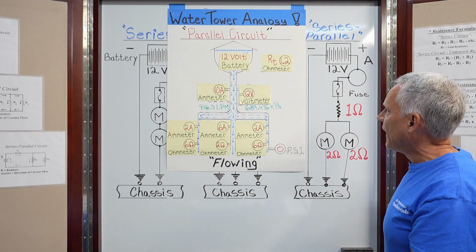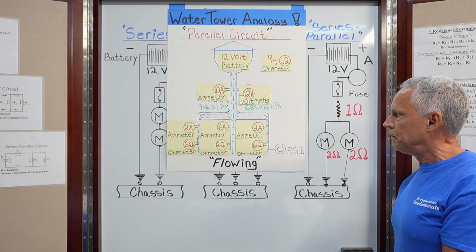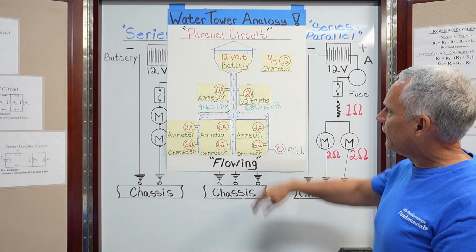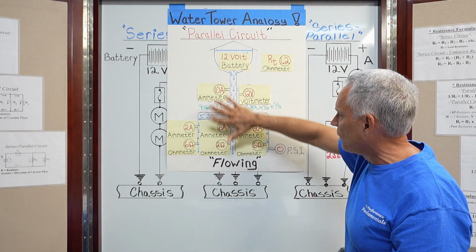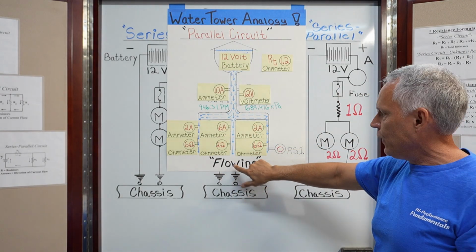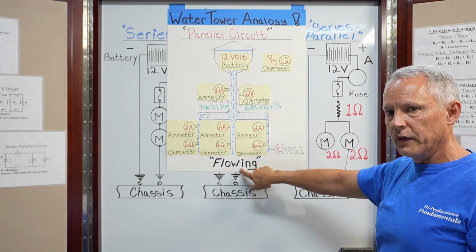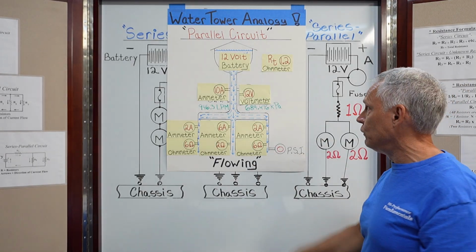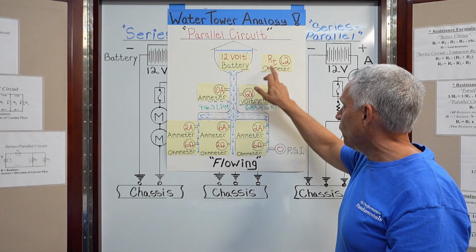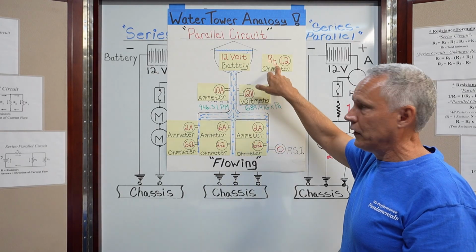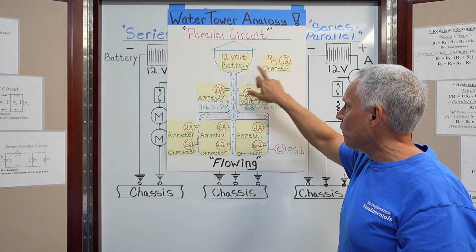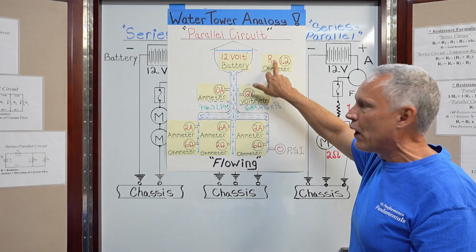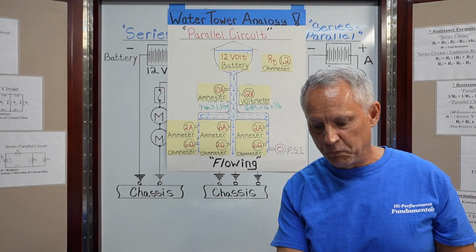Okay, so I think that explains a parallel circuit in a little bit better way. Maybe something you can wrap your mind around. Just think about it as branches or legs, right? And keep in mind that when we're monitoring or testing all this, this circuit is flowing, right? And you never use an ohm meter in a flowing circuit. You want to isolate things, right? In an electrical circuit, you want to isolate things, all right? You don't use an ohm meter in an active functioning circuit. You would use an ammeter in that case, and then calculate the resistance, calculate the ohmage. You do not use an ohm meter in an active circuit. You use an ammeter once again, and you will then take that value and your voltage value and calculate the resistance. Okay? Hopefully that explains things a little bit better.